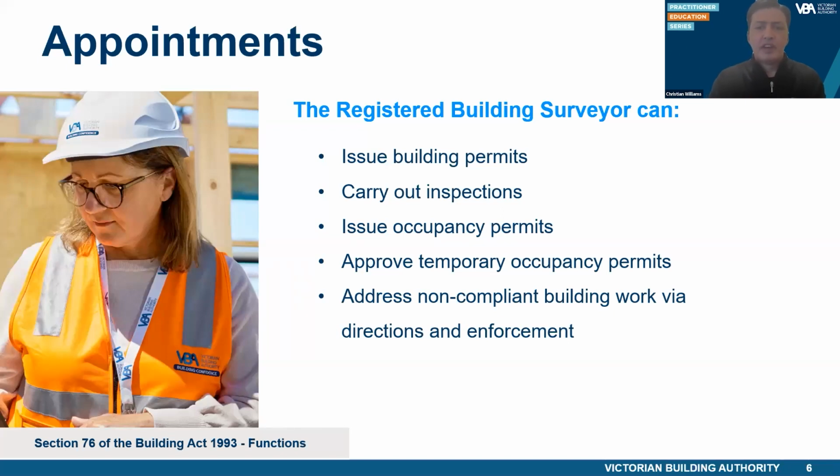A registered building surveyor is authorised to carry out the functions under Section 76 of the Building Act and any other functions conferred upon building surveyors, including assess building permit applications for compliance with the Building Act, regulations and NCC, issue building permits, occupancy permits and certificates of final inspection, conduct building inspections at mandatory notification stages, and take enforcement action.